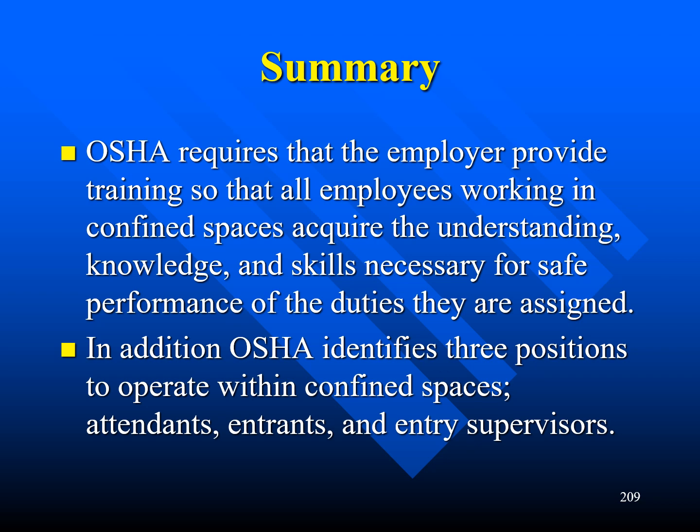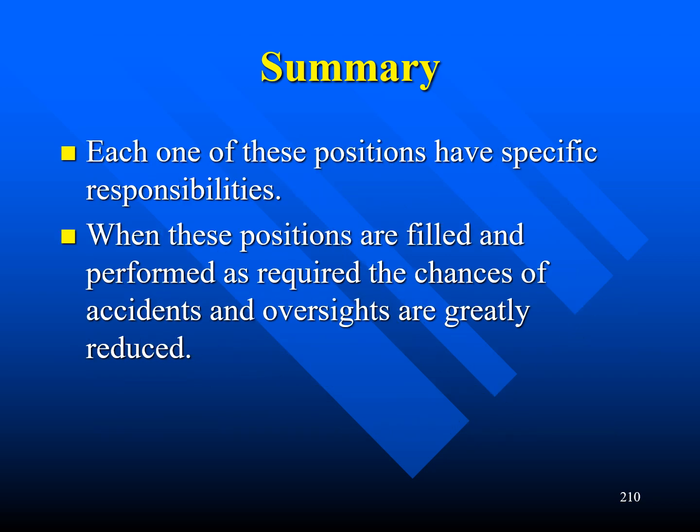Let's summarize Lesson 9. OSHA requires that the employer provide training so that all employees working in confined spaces acquire the understanding, knowledge, and skills necessary for safe performance of the duties they are assigned. In addition, OSHA identifies 3 positions to operate within confined spaces: attendants, entrants, and entry supervisors. Each one of these positions has specific responsibilities. When these positions are filled and performed as required, the chances of accidents and oversights are generally reduced.